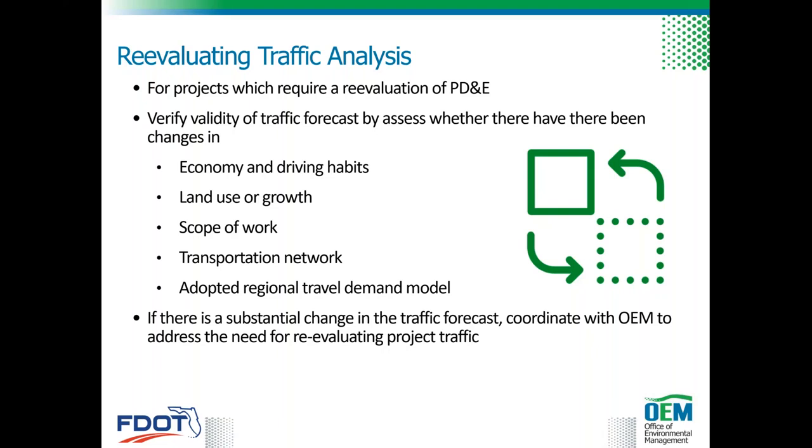The project manager, or PM, should verify the validity of the traffic forecast by assessing whether there have been changes in conditions or assumptions brought by substantial changes in the economy that may affect driving habits, such as an economic recession or sudden change in gas prices since the project traffic forecast was prepared. Another thing would be substantial changes in land use types or growth rates and patterns within the study area. A good example of this would be a large-scale development, such as sector plans approved near the study area, which have the potential to change traffic generation or travel patterns.